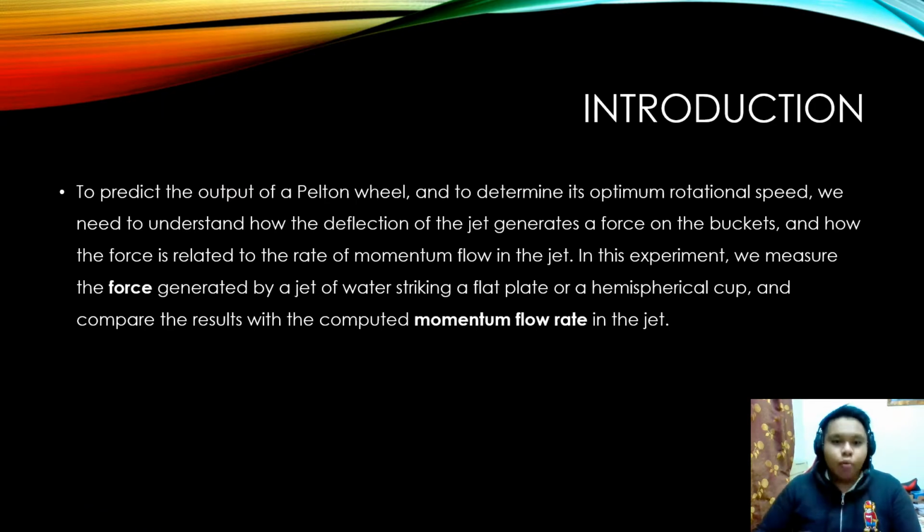To predict the output of a Pelton wheel and to determine its optimum rotational speed, we need to understand how the deflection of the jet generates a force on the buckets and how the force is related to the rate of momentum flow in the jet. In this experiment, we'll measure the force generated by a jet of water striking a flat plate or a hemispherical cup, and compare the results with the computed momentum flow rate in the jet.